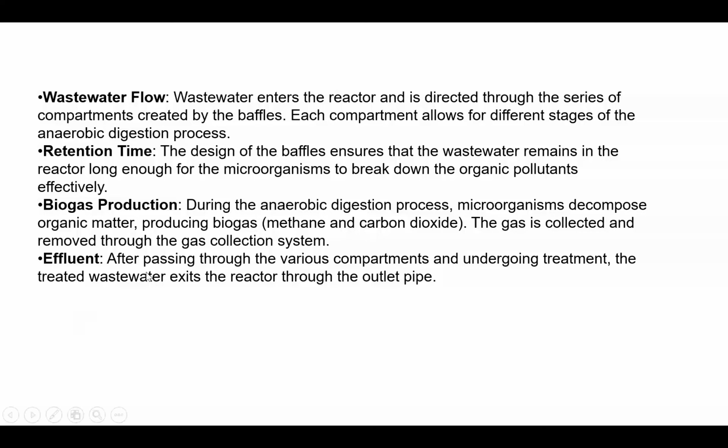Effluent: after passing through the various compartments and undergoing treatment, the treated wastewater exits the reactor through the outlet pipe. Even if it's treated through all these compartments, we need a tertiary step to disinfect the water if you want to consume it.